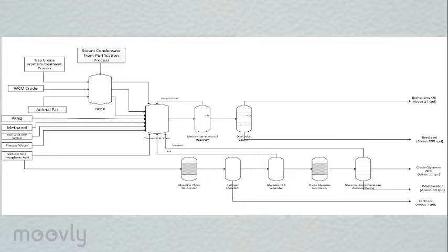Lastly, in the process of glycerin demethanolizing and dewatering, the filtered neutralized glycerin phase is distilled. In the column, methanol and water are separated from the glycerin, and the second column separates water and methanol. Crude glycerin, 80%, is discharged to the storage tank.